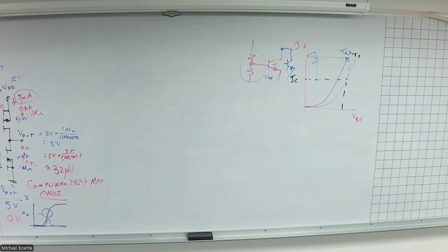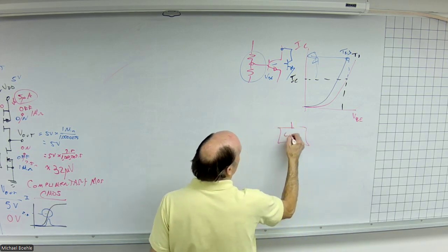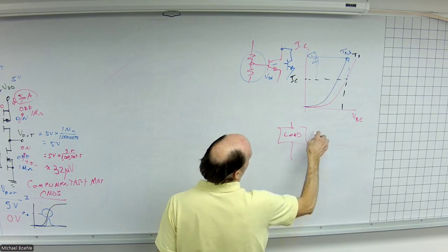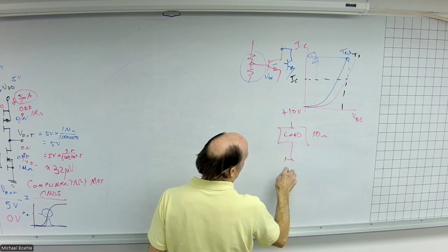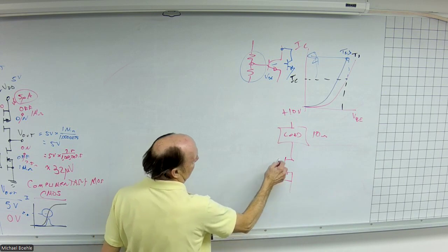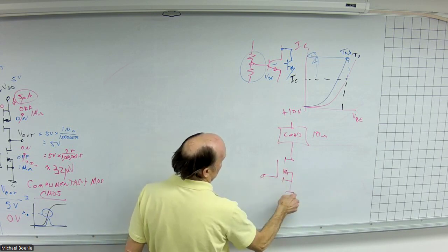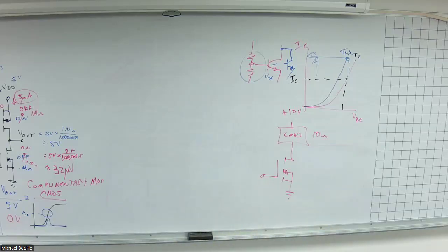So beyond that, the setup for this is going to be very similar, right? Whatever we have, if we have some load here, whatever that load resistance is, and I take my power MOSFET in here. In this example, it needs to be able to handle at least 1 amp. And I think there's a table of these devices at the bottom of page 495.